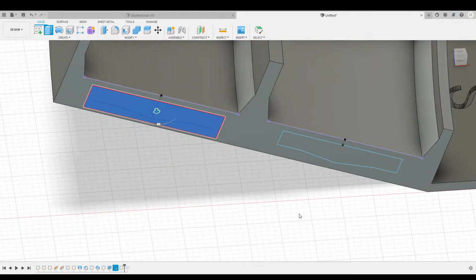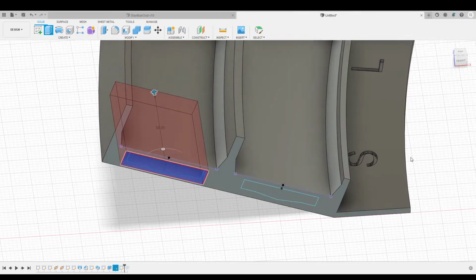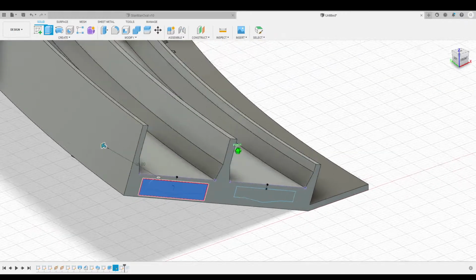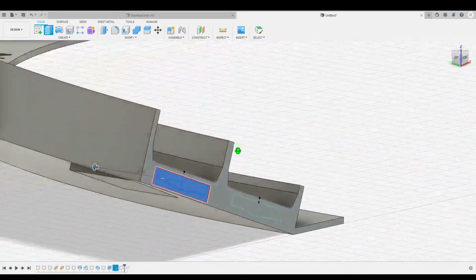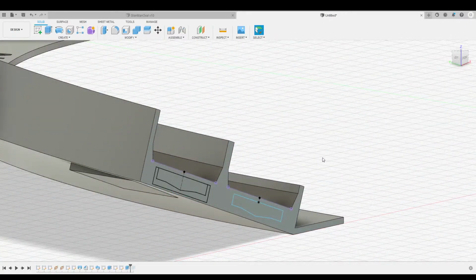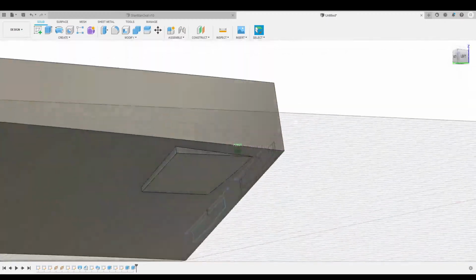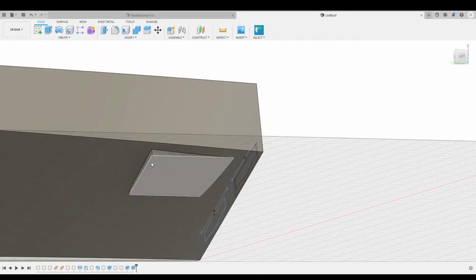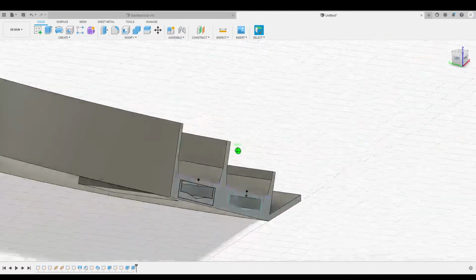negative 36. Oh, I gotta click it. Negative 36. So we're going to give it a 2 millimeter buffer on the outside, but I don't want to cut, I want to join. And so you can see that's going to stick through. And I'm going to say, okay. And now when I go to do my next step, it's now cut through there, and it's all contained. So then we can put a nice smooth curve on that later on, once we get to that step.